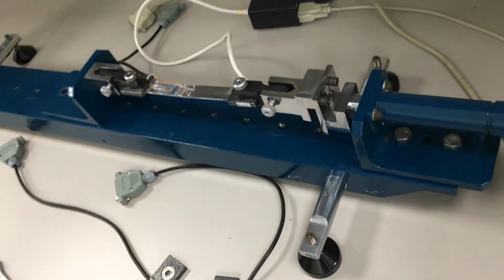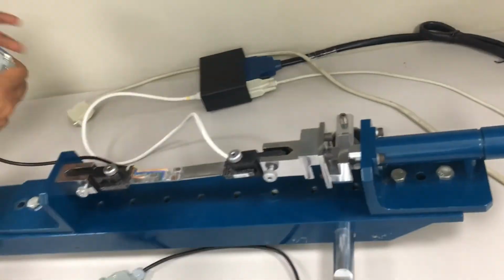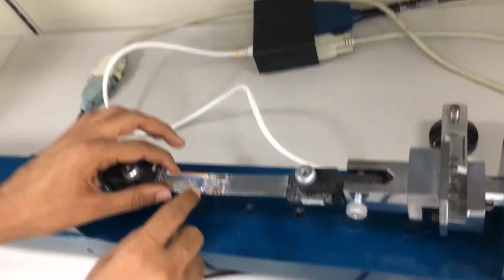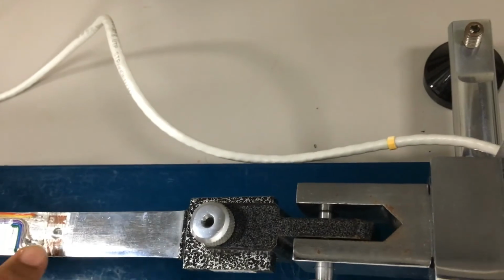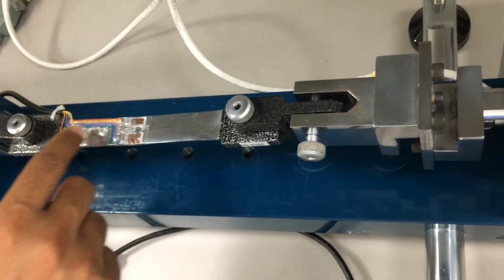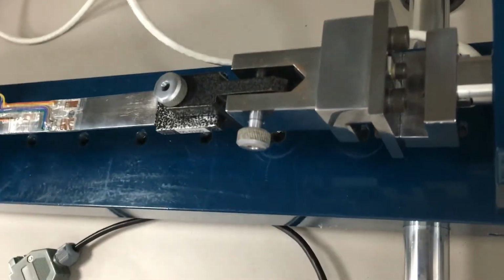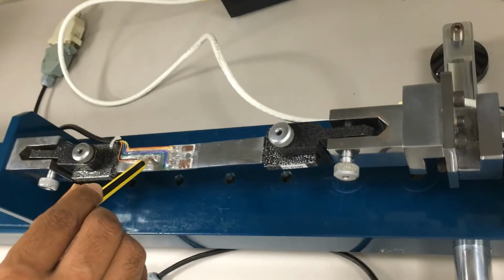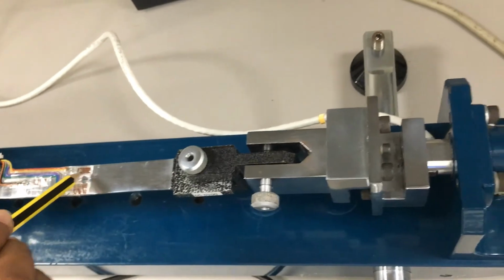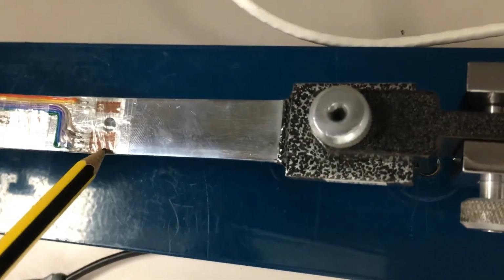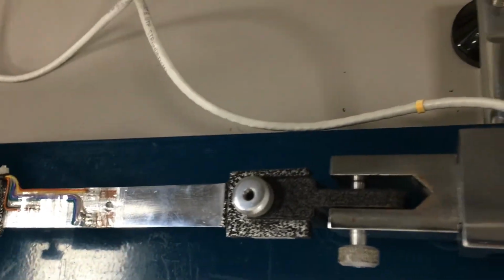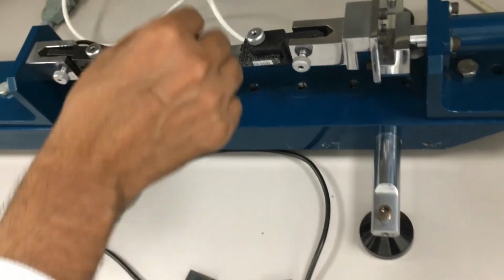Good. So it's ready now, and we need to connect the sensors to be able to measure all longitudinal positions. So we have 1, 2, 3, 4 sensors, and we will be able to detect the stress concentration at this position far away from the circle, and another on this y-axis we have 2 sensors, one far from the circle and one close to the circle, and another one from the other side, and then we can discuss the differences between all values of stresses.